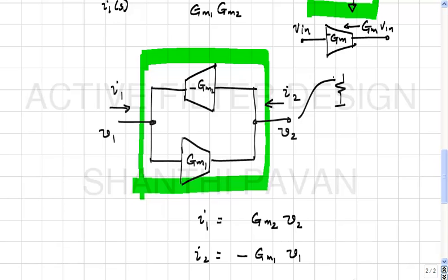If I put a capacitor, what will happen? Inductor. If I put an inductor, it will look like a capacitor, right? If I put a resistor and a capacitor in parallel, how will it look? Inductor and resistor in series. The Z looking in here, the Z at port 2, will be proportional to the Y at port 1.